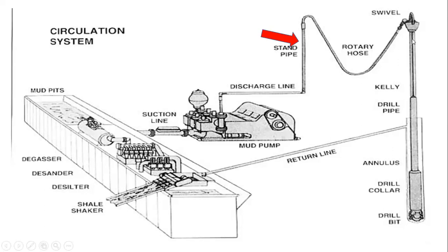Now when you look at this component, this is the drilling string. The drill string is a combination of joint drill pipes, okay, which are connected in series, very, very long. For those of us who know Koforidua, it can be as long as from here, from main campus to the roundabout. So let's say we can have it as about 5 kilometers in length. So it contains sections or joints of drill pipes. So it's very, very long. But then this standpipe helps to raise the mud to a certain height before it moves through the drill pipes.